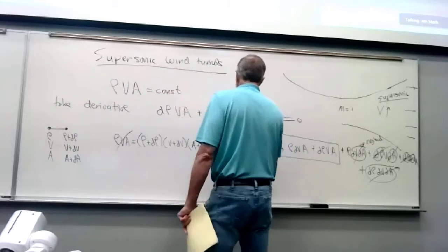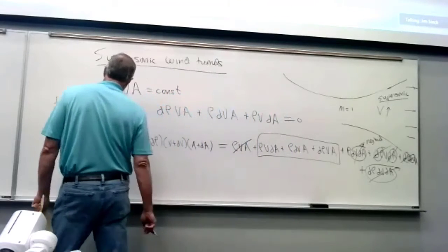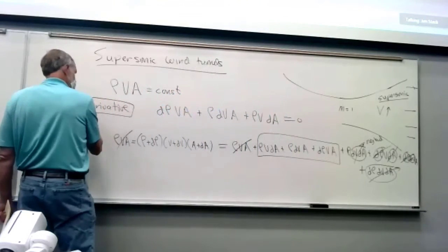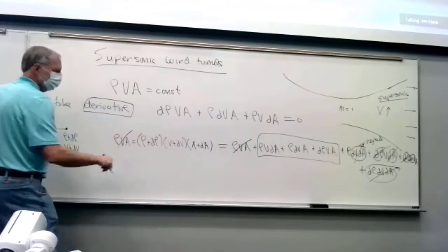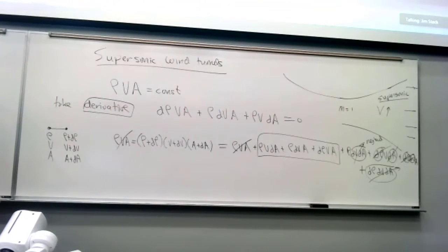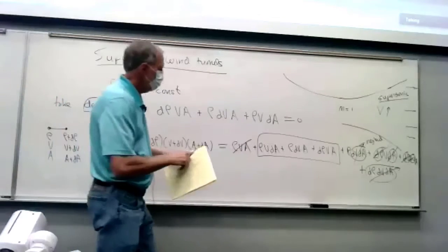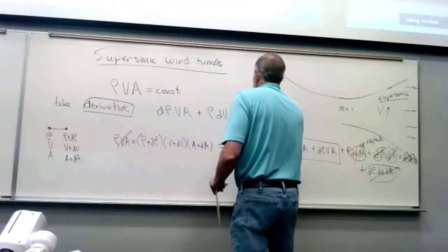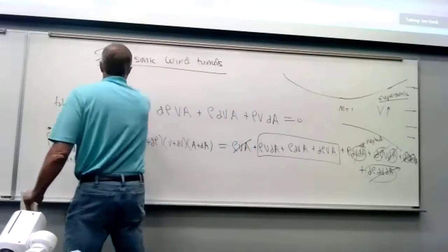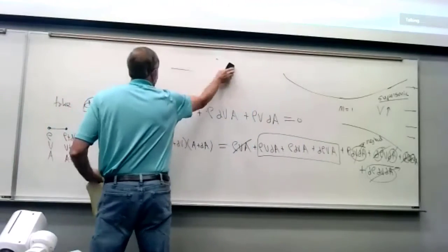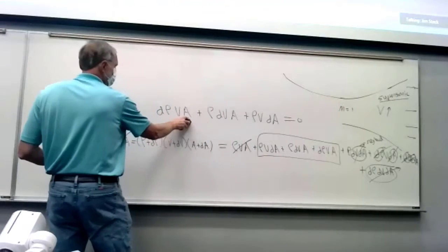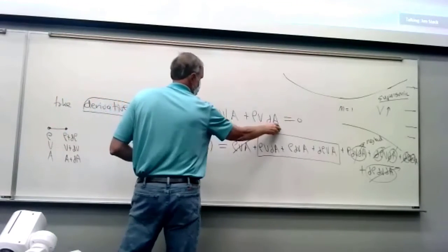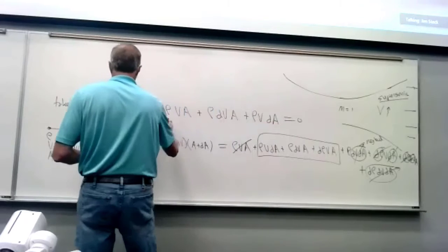So there's two ways you can get this formula. Either differentiate, or essentially do what a derivative is: you make a small change, and then you take the limit as those changes get really small. Anyway, we're going to take this equation and do a bunch of algebra on it so that we can learn about flow when the area is changing, related to velocity and density changes.